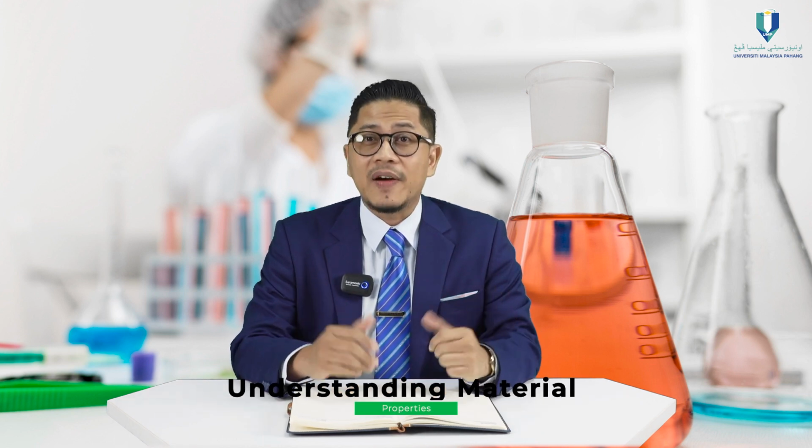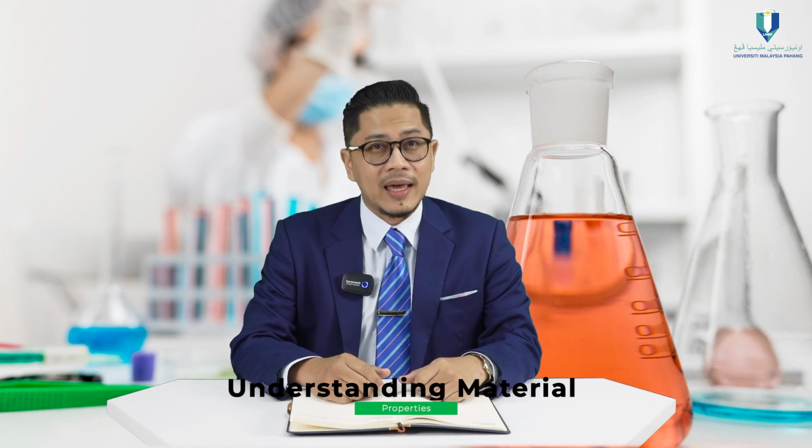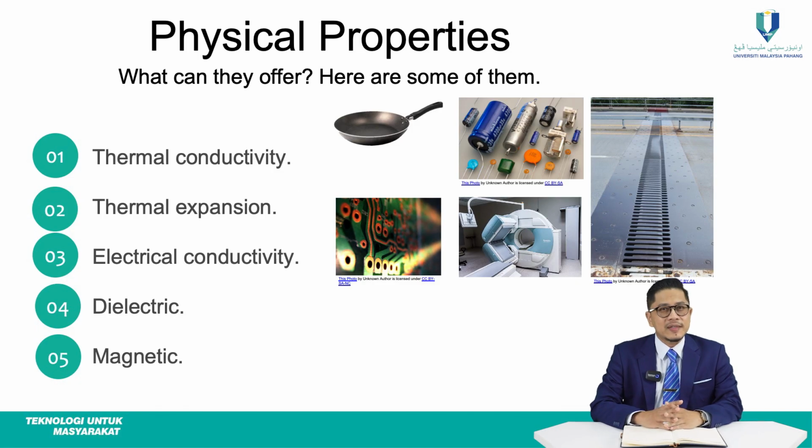These properties can be divided into two main categories, the physical and mechanical. Physical properties refer to how a material behaves under certain conditions such as temperature or pressure. One important physical property is thermal conductivity. This property describes how well a material conducts heat. Materials with high thermal conductivity such as metals are used in applications like heat exchangers and cooking utensils. Materials with low thermal conductivity like ceramics and plastics are used for insulation.